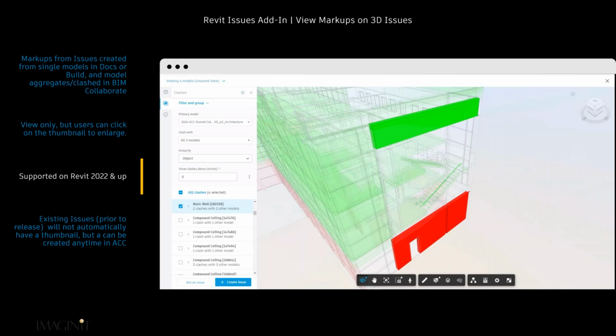So same idea from Navisworks. We can capture issues that are created via web or mobile. I guess primarily probably via web for our coordination models, but in Navisworks we have the issues tool where we can navigate to the issues, either mark them as I suppose the different clashes, and then those would also link to Revit to actually update the models to correct them.